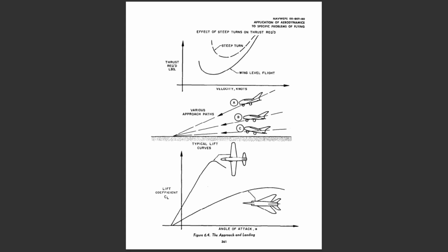For the conditions of steady flight, angle of attack is the primary control of airspeed, and power setting is the primary control of rate of climb and descent. This is especially true during the steady approach to landing. Of course, the ability of the power plant to produce rapid changes in thrust will affect the specific technique to be used. If the power plant is not capable of producing immediate controlled changes in thrust, the operating technique must account for this deficiency.